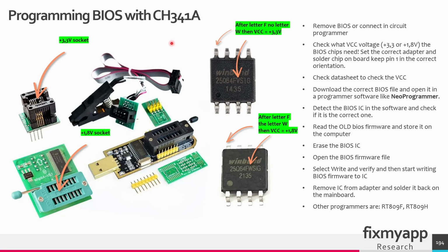This programmer is a USB to serial interface chip that is used for SPI, I2C and UART communications. It's commonly used as an EEPROM and SPI flash programmer, making it useful for BIOS flashing, firmware recovery and debugging embedded systems. In this case, this programmer is used to flash BIOS ICs. I will not explain how to flash the BIOS, because there are enough videos on YouTube where you can learn how to use this device.